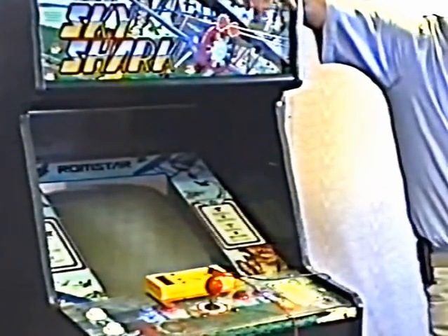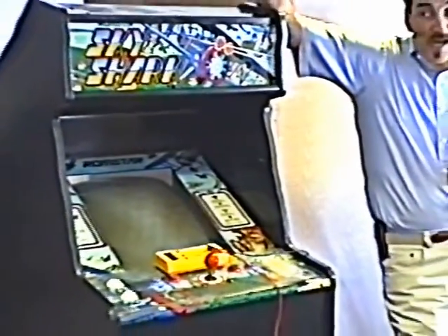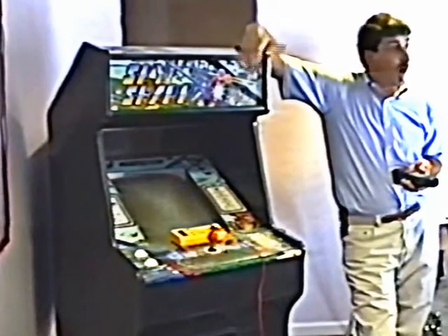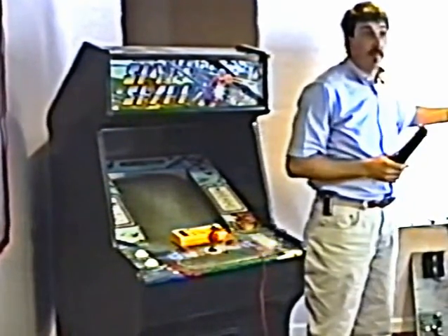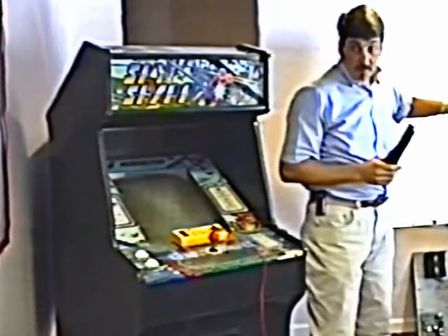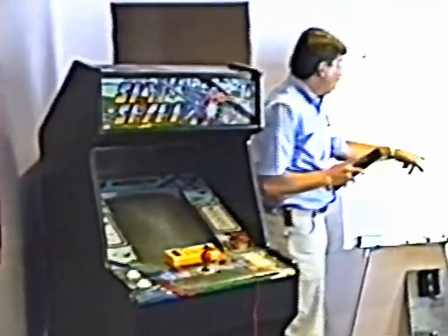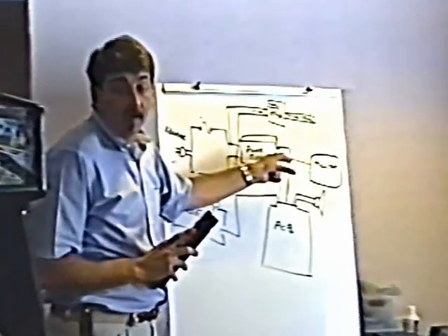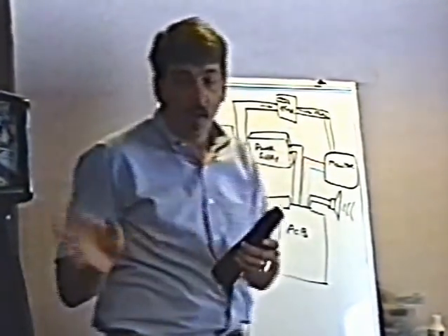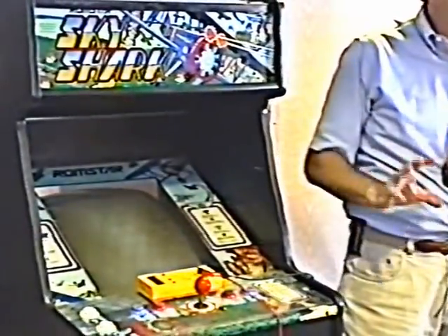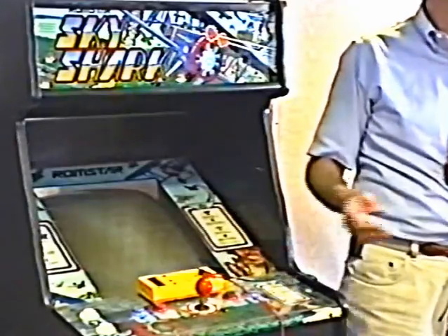See if you hear all the game sounds. If you hear all the game sounds, that must mean the computer's working. If the computer's working, the power supply's got to be working too. If the computer's doing its thing, the power supply's good. So right away, as soon as you coin it up and you hear all the game sounds, you know that the power supply is good, it's plugged in, the computer board is good.